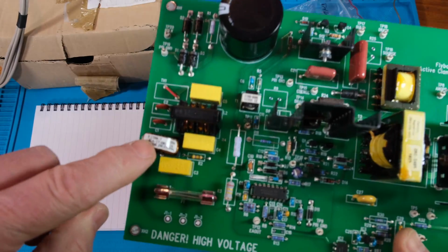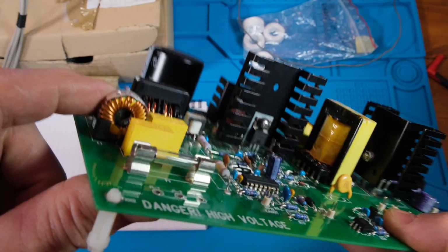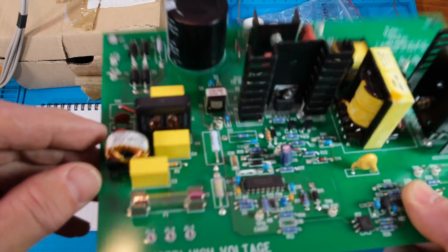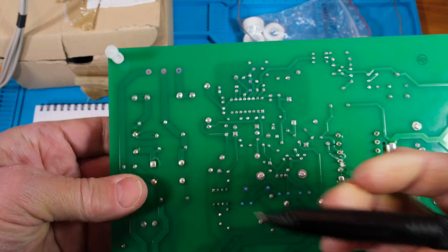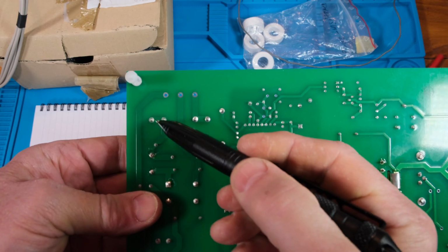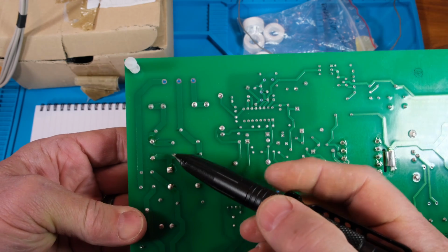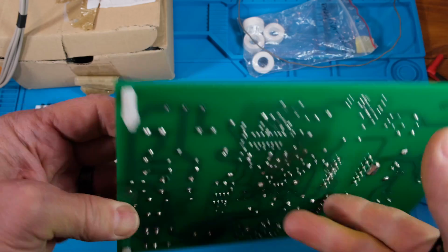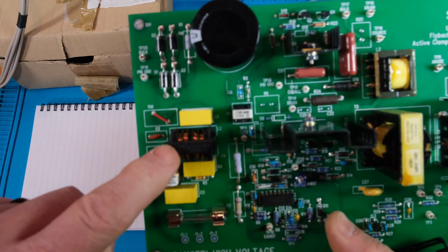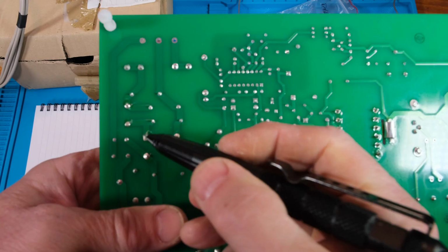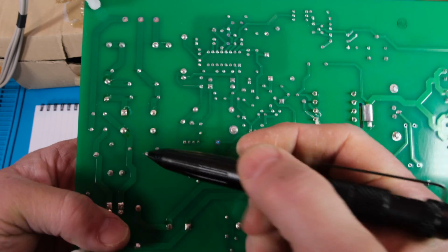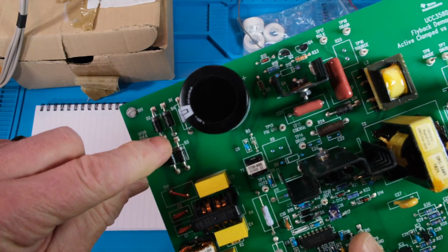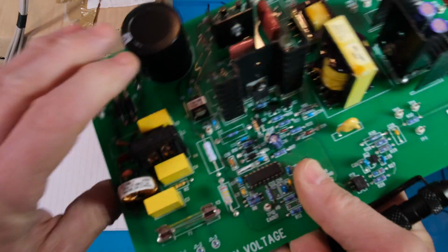Now the break would be this inductor. So this is not the common mode choke. This is a differential mode. This is a single winding, just two pins on it. So the current comes this way, goes through the choke, and then gets to this break. And then there's another break. And that's this common mode choke. Okay? So it comes here, it goes through the winding, comes out here. Then comes up to the diodes right here. See, here's the diodes right here. Okay? So that's how the line gets up there.